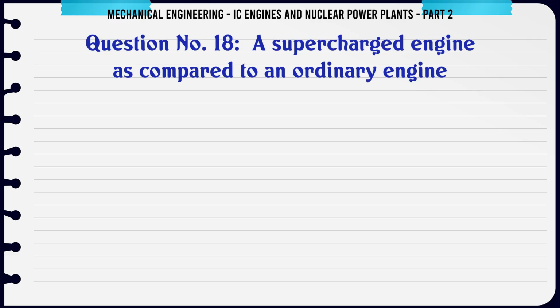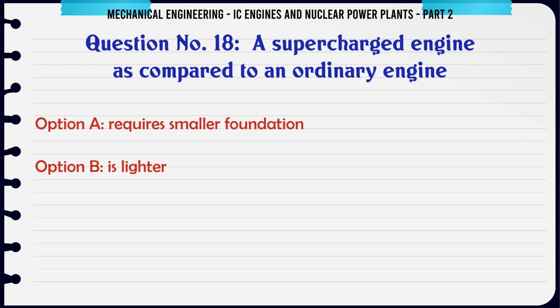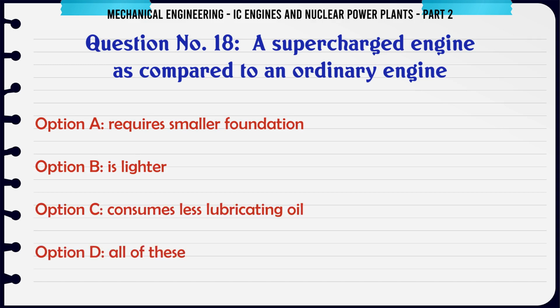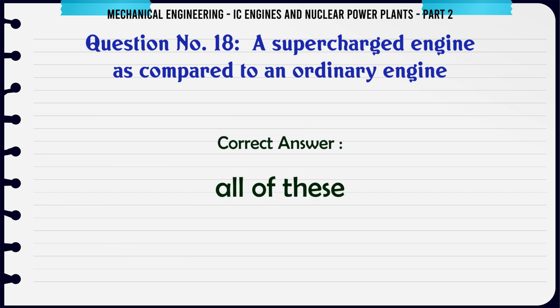A supercharged engine as compared to an ordinary engine. A. Requires smaller foundation. B. Is lighter. C. Consumes less lubricating oil. D. All of these. The correct answer is all of these.